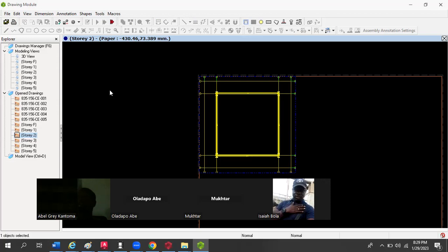We're able to run a model. We're able to import steel cross-section. Like I said, all you need to do is just sketch out a steel cross-section anyhow, irrespective of the shape of that steel cross-section. You can just sketch it from your AutoCAD and then just import it. For as long as your drawing is the way it should be, Prokon Structure will, all you need to do is just assign the type of chord that is there. If it is a diagonal chord, you assign it there. So just tell Prokon Structure, this is a diagonal chord, this is a top chord, this is a bottom chord. Once you tell it what you are assigning as each of those chords, that is all. It recognizes them. You run your model, irrespective of how the shape of that model is coming. It's very easy. You can see how the tools are.